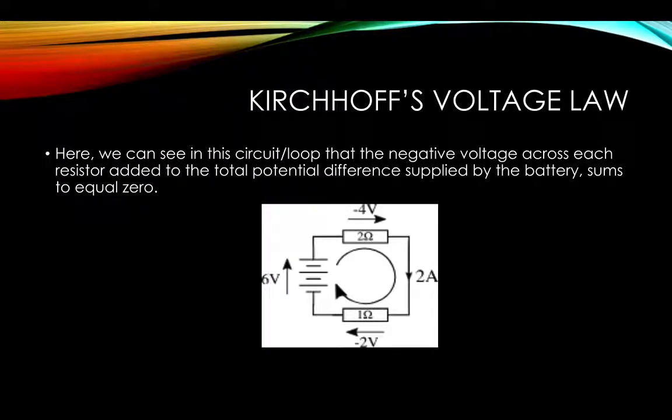And then we also have Kirchhoff's voltage law. It's his second law, and it states that the sum of all voltages around any closed loop in a circuit must equal zero. This is a consequence of charge conservation, actually, and also conservation of energy. As charge carriers flow through a circuit, passing through a component, they either gain or lose electrical energy, depending on the component. The negative of the work done by these electrical forces on a unit of charge which passes through a component is called the voltage across the component.